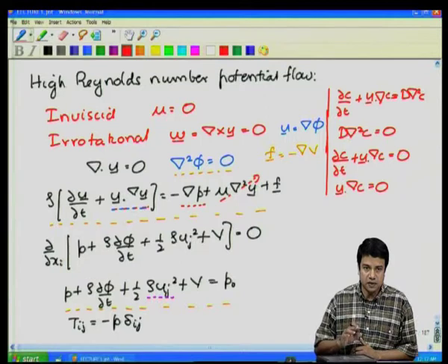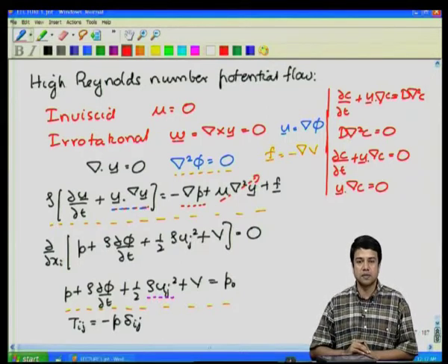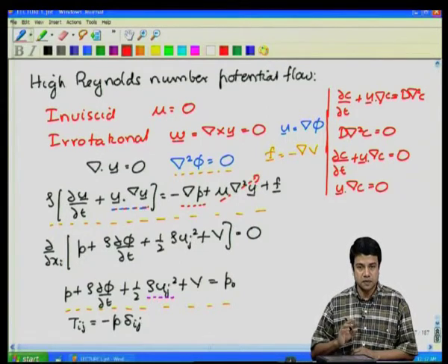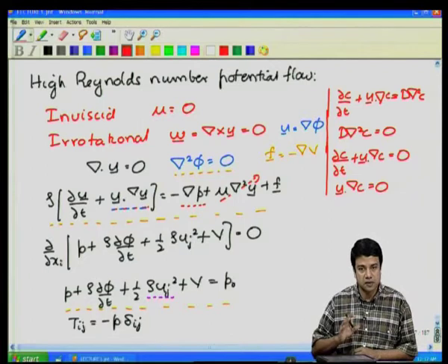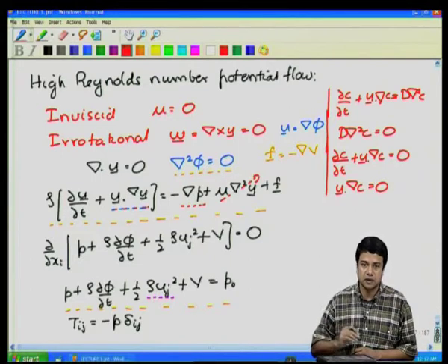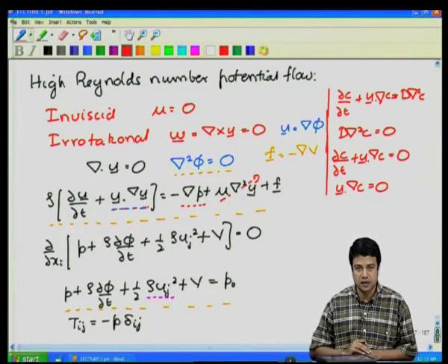Therefore, I get a non-trivial result for the relationship between the pressure and the velocity. So, we are solving the same convection dominated regime, except that we have this additional fluid pressure here, and that makes all the difference. That is why you have this potential flow regime in fluid mechanics. You do not have equivalent problems in heat and mass transfer. It is because of the fluid pressure.